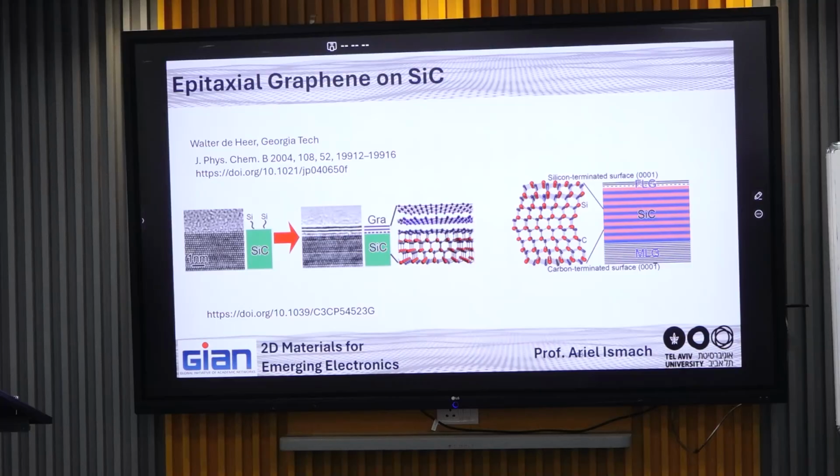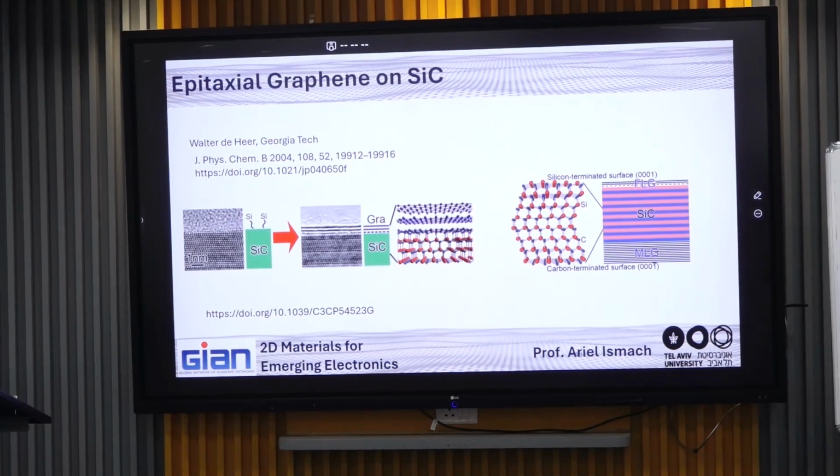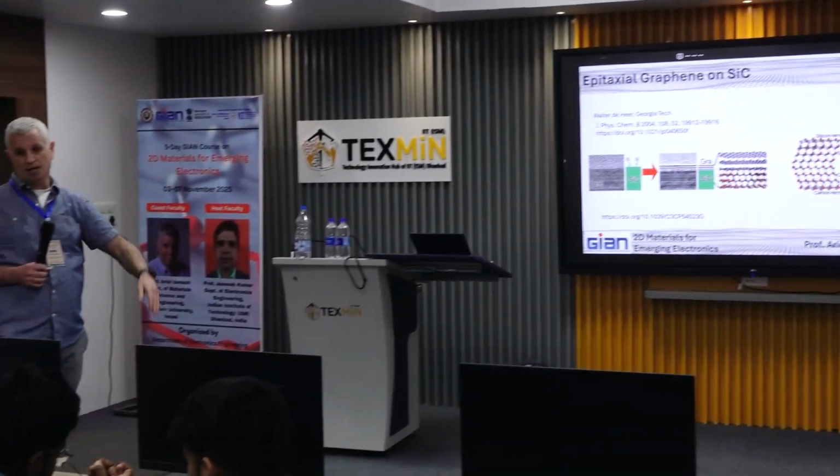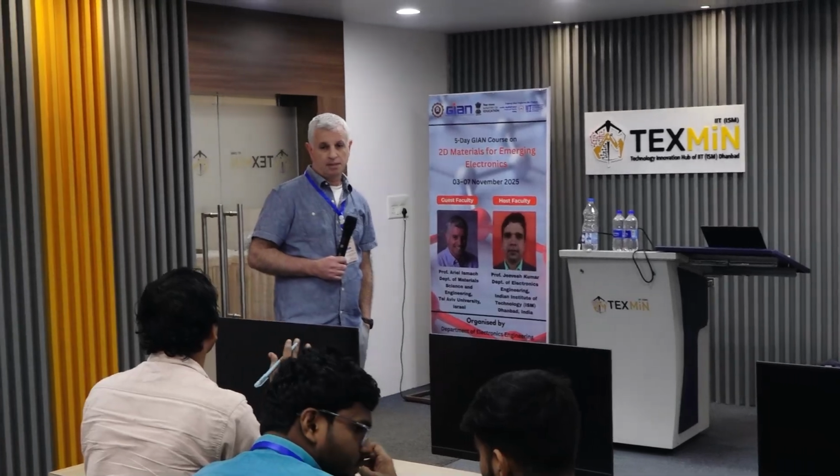So here, for making this epitaxial graphene, initially you have a substrate of silicon carbide, a bulk, I mean, a wafer. So how much time do you keep on removing the silicon? So again, first of all, you just remove the silicon only in the top layer and then you peel the carbon layer from there. Is that right? Yes, you can do that. Also, you can use the silicon carbide to build the devices. You can build your devices directly on the silicon carbide.